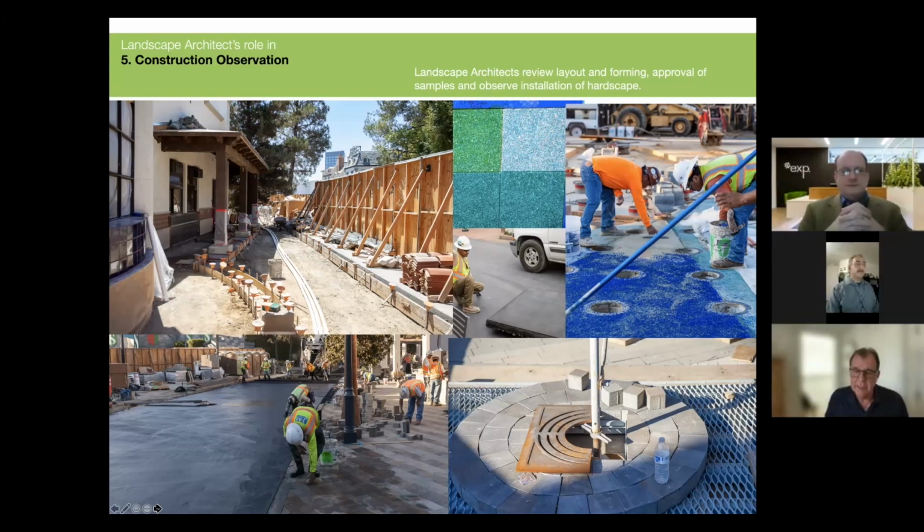I might mention that after we did this install, we learned that because of the volume of pressure washing and the way the maintenance crews did that, they were putting too much water into the tree. And so that grate on the top was changed to eliminate the spaces that you see and then add a collar along the top to prevent water from running into the tree root ball.